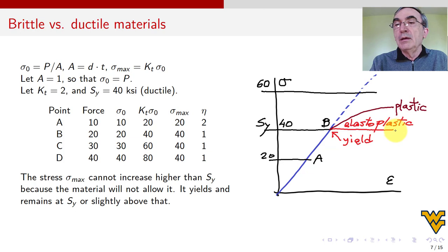All right. And now this elastoplastic model, where you go like this and then flat, is a useful model to solve problems of crashworthiness and other problems, where you don't want to deal with this curve, which complicates your solution. We're not going to do this, but I'm just telling you, this is not just something I made up. It's very common to assume the material is elastoplastic, and it's a good approximation. A lot of stuff has been designed with this approximation.